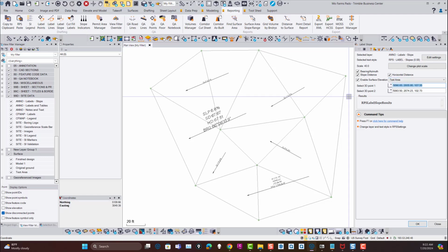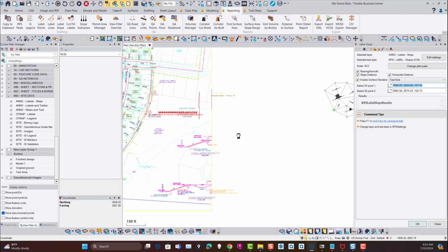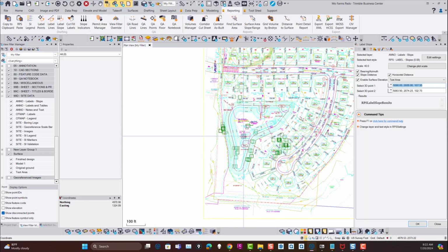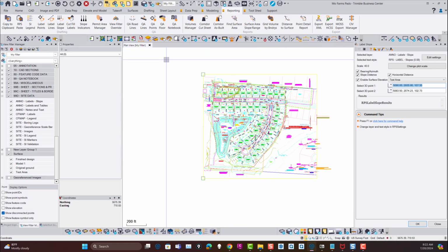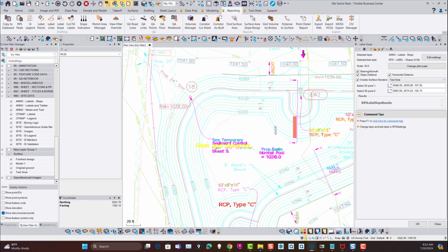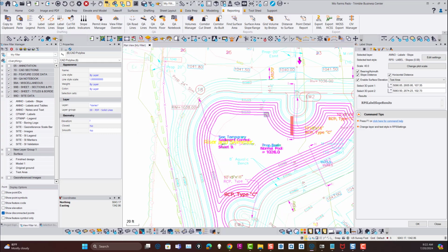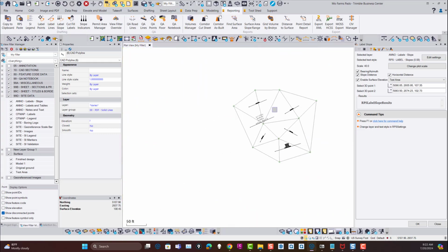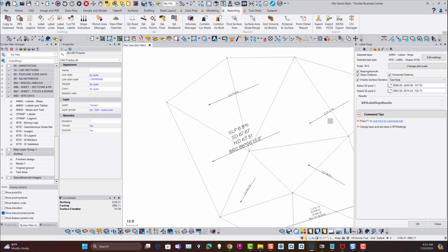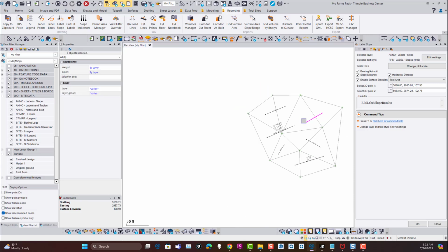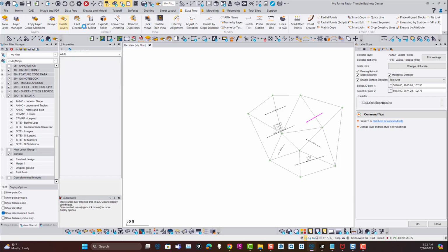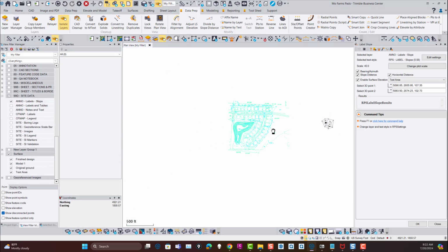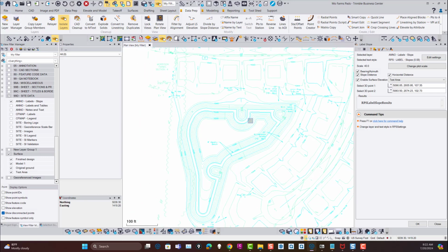If we take a look at how we would use it in other modes, if we were looking over here on this part of the drawing, what I could do is pick a couple of lines here. If I just pick some of these contour lines, like these guys here, and then let's say I come over here and I pick some of the labels I've already created, because I want to keep these layers visible. At this point I can use the RockPile Isolate Layers command, which is found in the data prep toolbox, and that allows you to isolate just the layers that you've selected. Now it's more than one layer in this case.